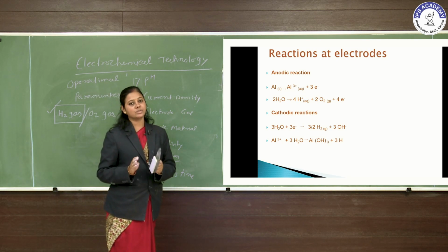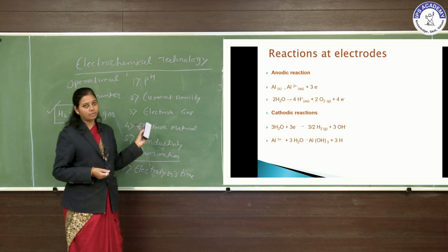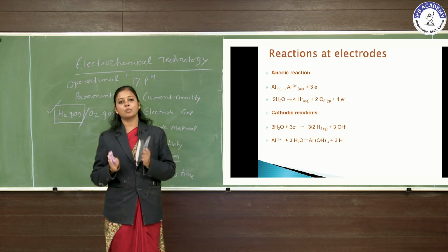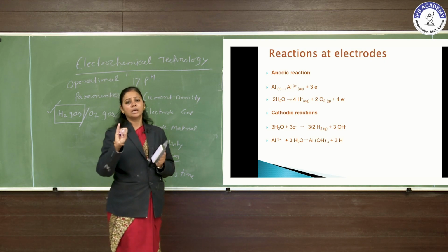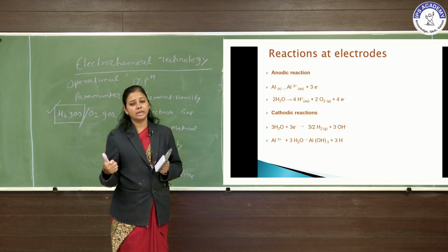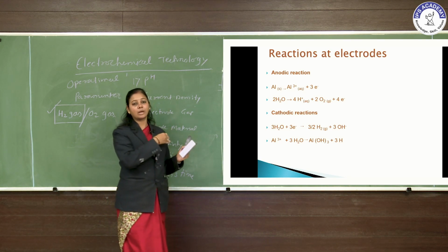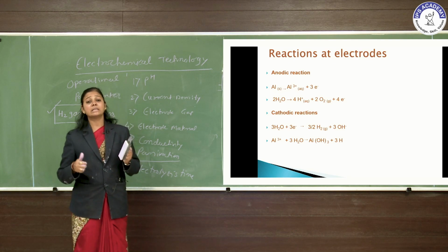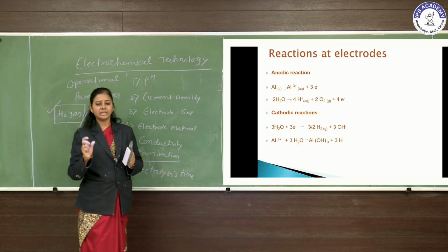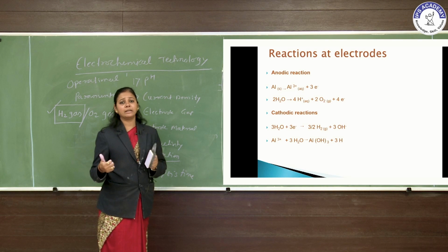So this is all about the treatment technology, an efficient treatment technology that can be applied to small scale textile industries. I can strongly say this electrocoagulation treatment technology can be easily applied to small scale industries, because it does not require on-site treatment. It does not generate a huge amount of sludge. The sludge generated is easily dewatered, meaning there is no bound water in it. It is an environment friendly treatment technology.